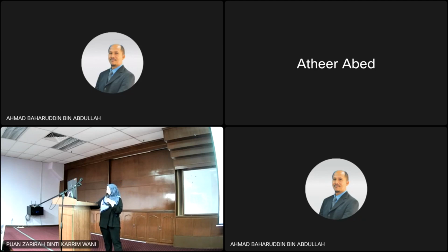So I think that's all from me. As a conclusion, the dimensional stability is not affected much by the parameter setting, whether the same parameter or not. And the region examined in the bimetal structure by EDX contains chromium at the interlayer zone, even though there's no diffusion of composition on both sides. And the hardness value is better on the forged specimen compared to the non-forged specimen. That's all from me. Thank you.